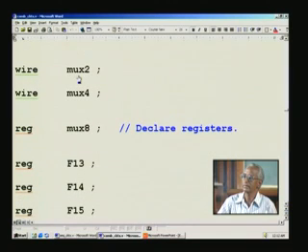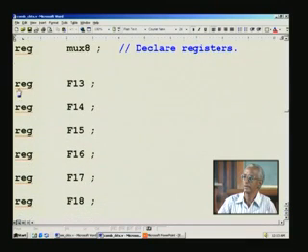And once again you see these are all where we did not use always block, we used assign statement for this, so we use a wire here, and we used an always block for mux site, therefore it is a reg, and these are all in always positive edge. In sequential circuits I think we have used this, that is why we have declared as reg.